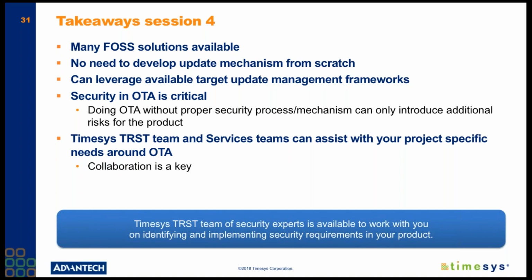So it's more of a gateway architecture, where the gateway itself can download the OTA image from a server, and once it downloads and updates, the gateway can then go ahead and update any sensors or other devices connected to it.